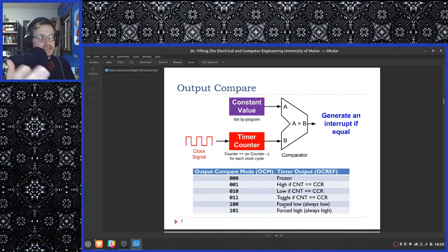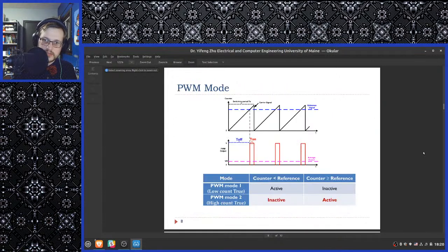You can time stuff. It's kind of funny, because it's like, what do you do with a timer? You time things. But that's what capture mode is useful for. It's necessary to save the value of the counter register in those instances because otherwise, how are you going to save it for later and do the subtraction, right? Fancier ones probably perform the subtraction themselves.